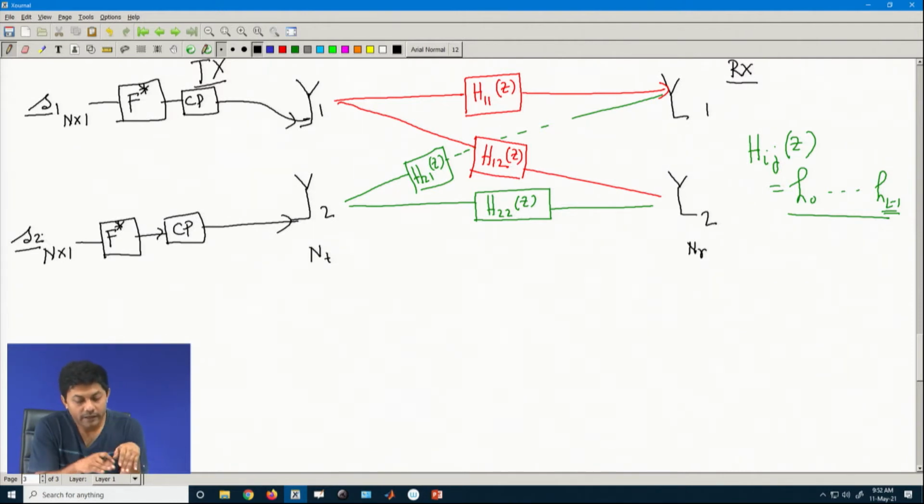Now, if you notice how a non waveform MIMO works, at a time every antenna will be delivering one individual data. Here also it is happening the same way, but now there is a catch. In the earlier case, plain MIMO, it was more on the spatial domain, meaning at a particular time your channel is structured, but now that is not the case, because every antenna is getting a serial data of n plus k length.